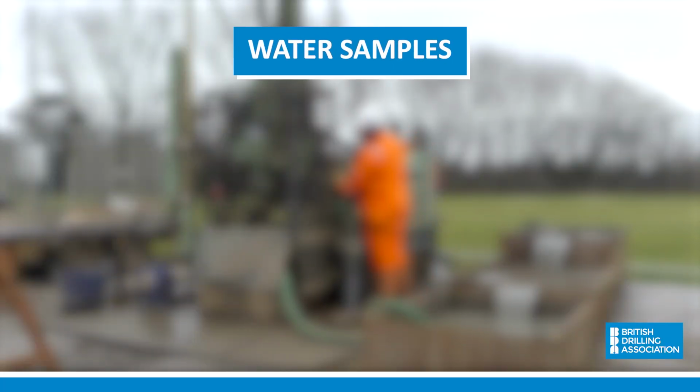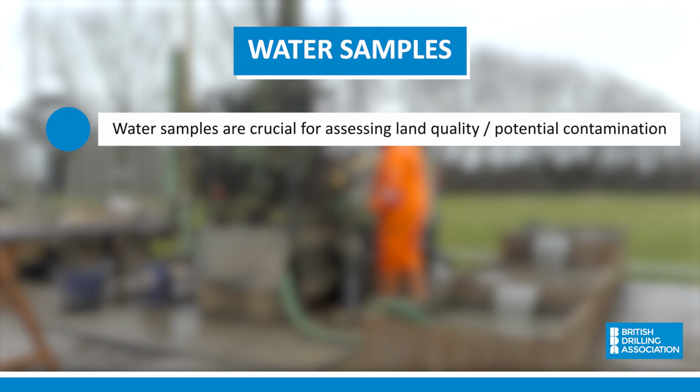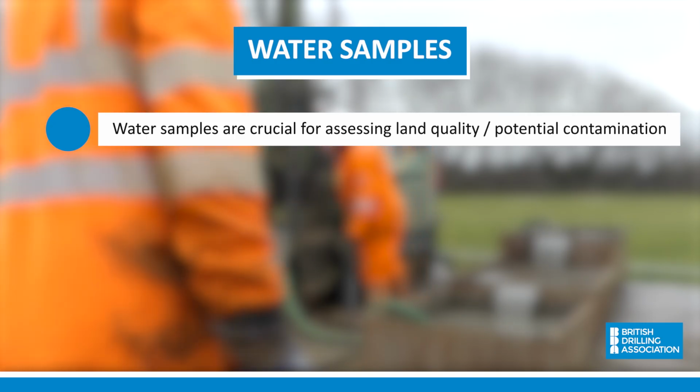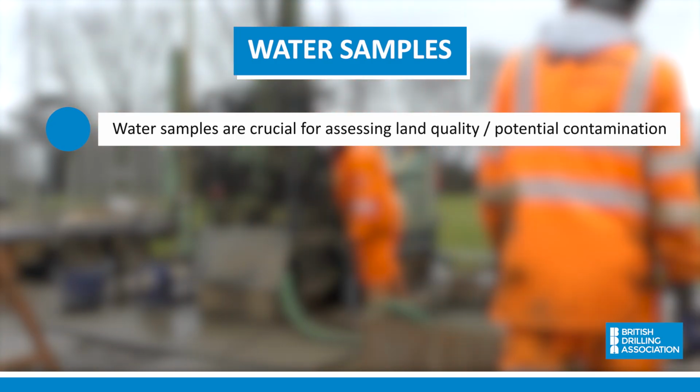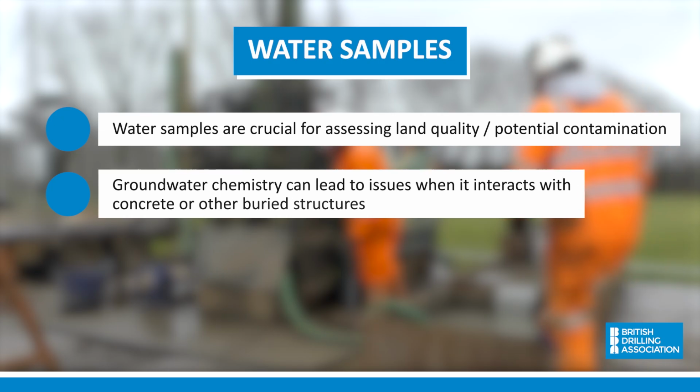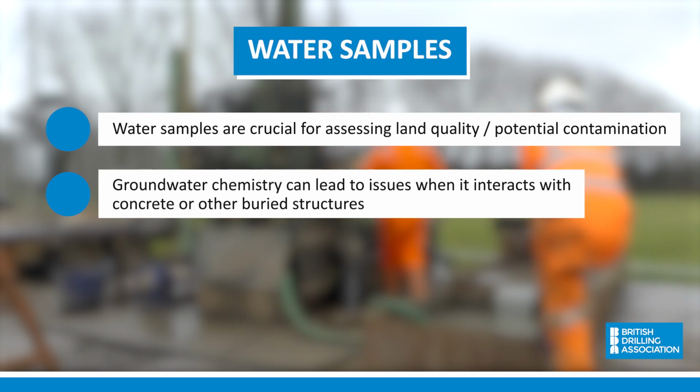The groundwater chemistry across sites can be very important when assessing land quality and looking for potential contamination. However, in certain parts of the UK, the groundwater chemistry can be aggressive, which can lead to adverse chemical reactions with concrete and other buried structures.